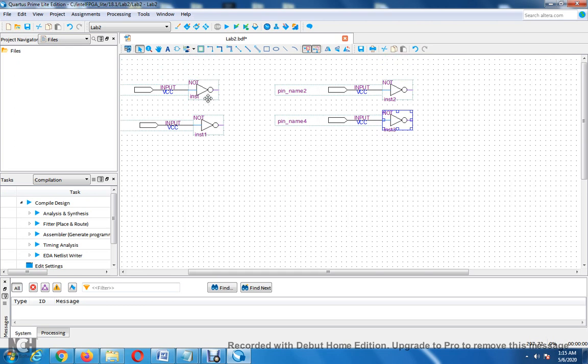Now, there's a little problem here. I'll show you. You have to have a piece of line between this pin marker and this. So you got to use the right arrow key to move it a little bit, and then you got a piece of line. Okay, you see that? So I use the right arrow key on the keyboard to nudge it. Is that enough? Oh, I know, they're not lined up. All right, so go here. Nudge it. Actually, the smallest bit of wire is enough.